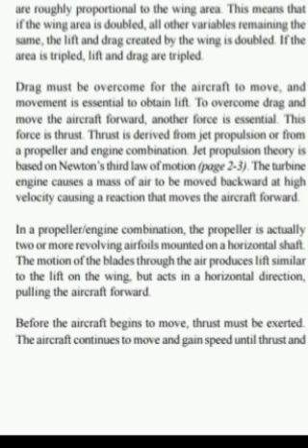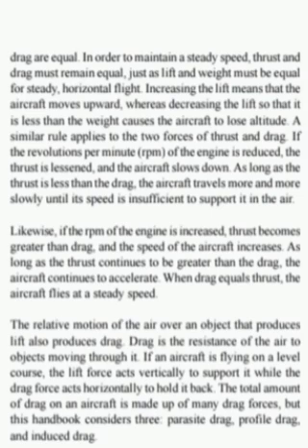Before the aircraft begins to move, thrust must be exerted. The aircraft continues to move and gain speed until thrust and drag are equal. In order to maintain a steady speed, thrust and drag must remain equal, just as lift and weight must be equal for steady horizontal flight. Increasing the lift means that the aircraft moves upward, whereas decreasing the lift so that it is less than the weight causes the aircraft to lose altitude. A similar rule applies to the two forces of thrust and drag.